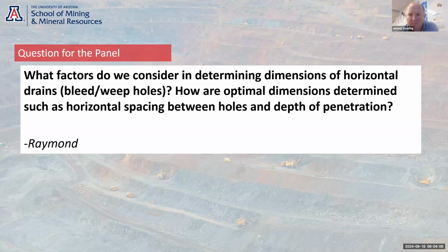Yeah, when you plan a drilling program, you have to think about the potential for unintended consequences of drilling the drains. So, for example, if you drill... Have you lost your audio? Yep. Yeah, so what Jeremy's saying is if you drill, you've got to think about what may go wrong. And I've been in a couple of situations where drains have caused slope failures by bringing shallow water into a failure surface, or by drilling too deep and bringing deep water into shallow failure surfaces. Yeah. So that's a key thing to think about.